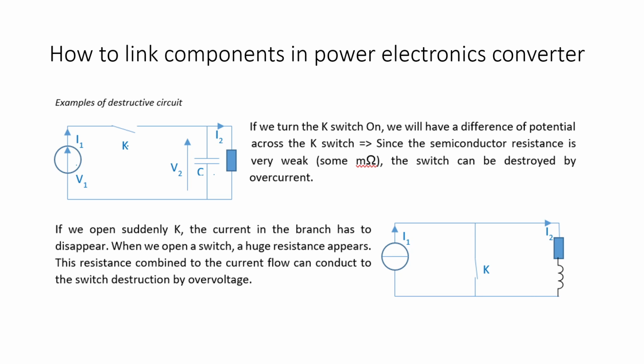So at the initial stage, this one behaves like zero resistance. Okay, zero resistance. This one is some resistance, right? Some value of ohms, and this one is 0 ohm. So all the current will flow through the capacitor, but not through this. That's why at the initial stage, large current flows through here, and it can destroy the capacitor. So the capacitor can block the current when it is fully charged, right?